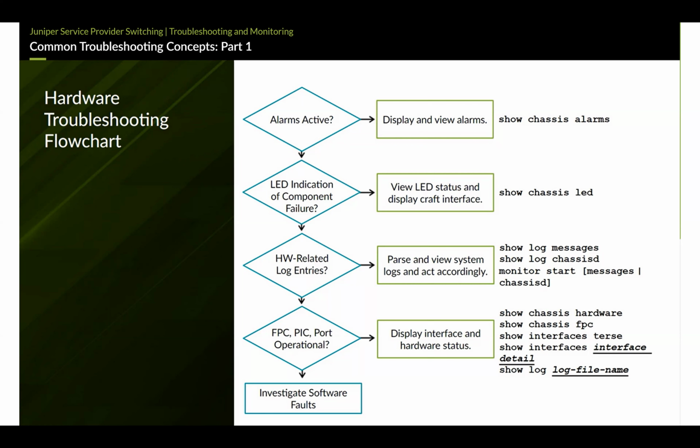Okay. So this is the hardware troubleshooting procedure: alarm, safety, LED indication, component failure, hardware related log entries, FPC, PIC, port operational, and investigate software faults.